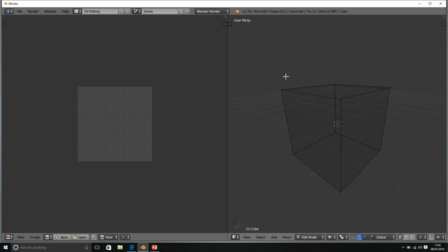So now we're going to create a better UV map by creating seams. To do that, we need to know which seams we are selecting. So we need to go into Edge Select mode. And if you're following along, try and do it exactly as I do it. So you want to try and create seams along edges where you can literally split your object.